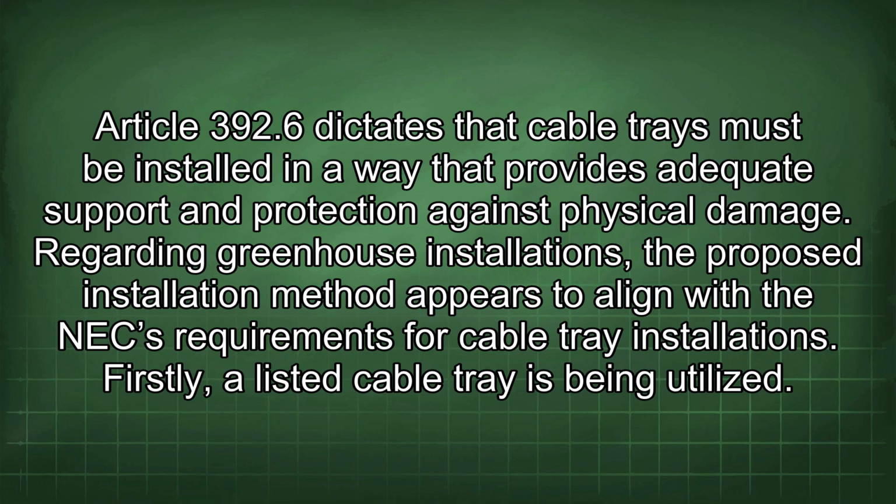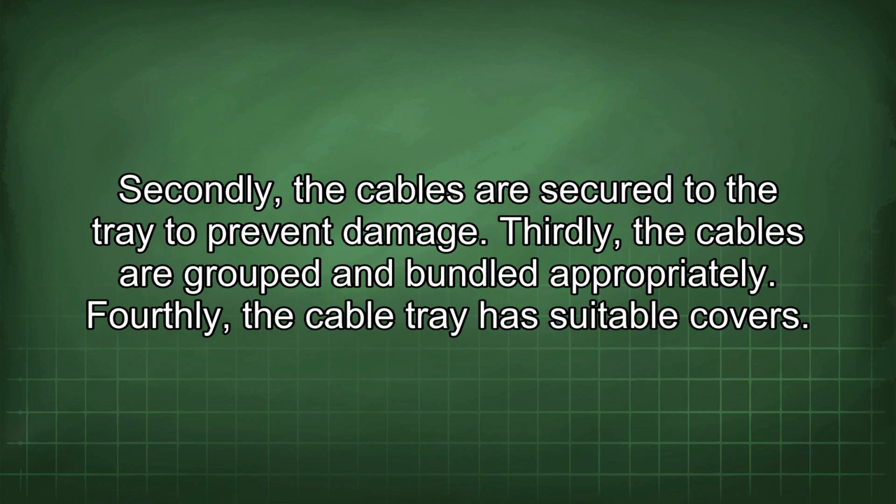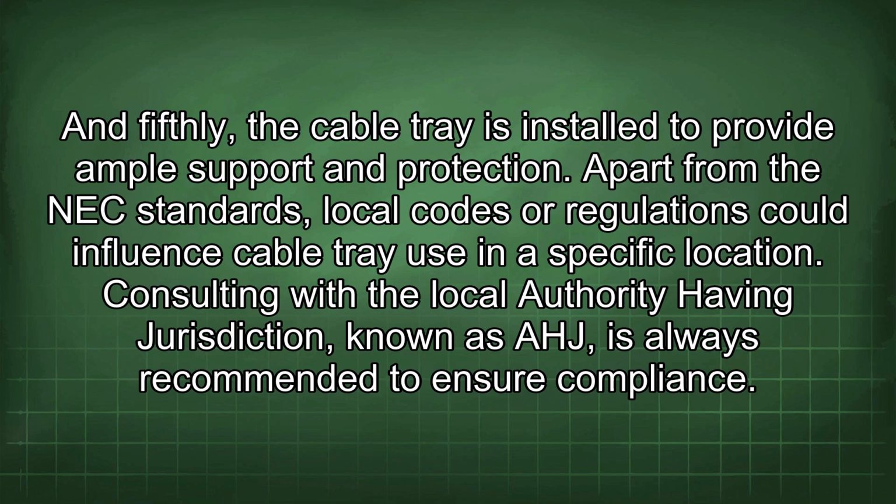Firstly, a listed cable tray is being utilized. Secondly, the cables are secured to the tray to prevent damage. Thirdly, the cables are grouped and bundled appropriately. Fourthly, the cable tray has suitable covers. And fifthly, the cable tray is installed to provide ample support and protection.